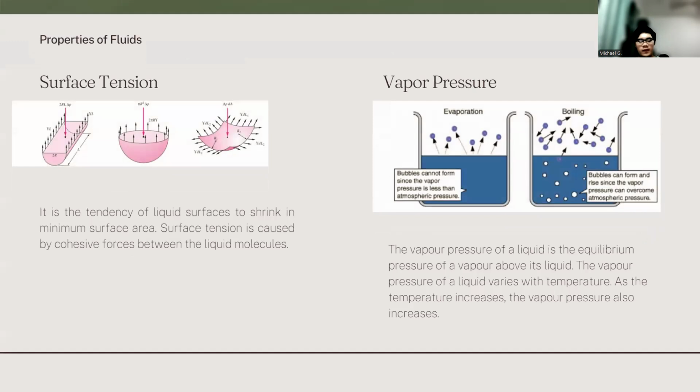Surface tension. The cohesive force between liquid molecules is responsible for the phenomenon known as surface tension. The molecules at the surface do not have other like molecules on all sides of them, and consequently, they cohere more strongly to those directly associated with them on the surface. Surface tension has dimension of force per unit length, or newton over meter, or of energy per unit area, or joule over meter squared.